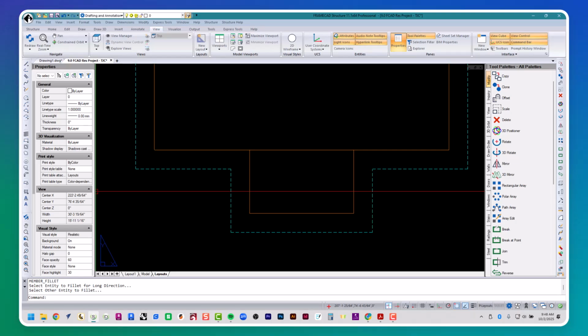Let's create the roof lines. Now that we have coded our support lines and roof lines, we can begin to create our roof lines by defining their rectangular footprints. Type in CRL. When defining the roof lines, we need to use 3 points. The first 2 points define the roof width and the orientation of the trusses, while the third point determines the extent of the roof trusses and the roof length.